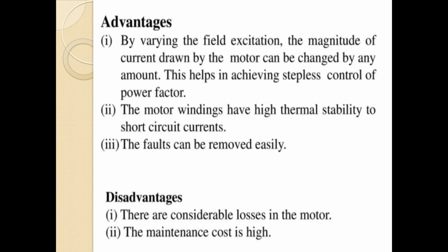Then the advantages. By varying the field excitation, the magnitude of current drawn by the motor can be changed by any amount. This helps in achieving stepless control of power factor. The motor windings have high thermal stability to short circuit current. Another advantage is that faults can be removed easily. Disadvantages: there are considerable losses in the motor, and the maintenance cost is high.